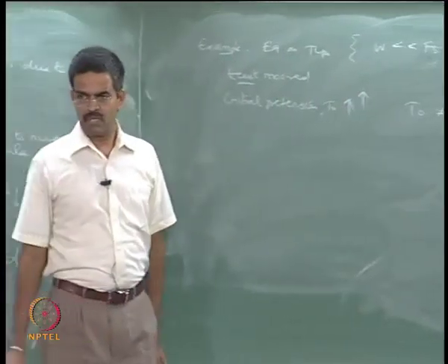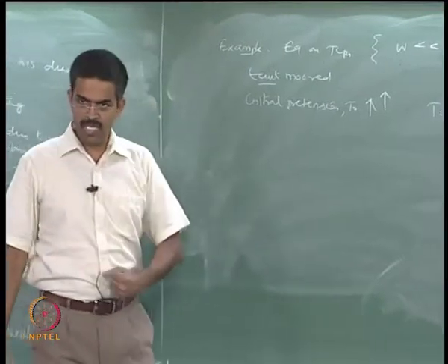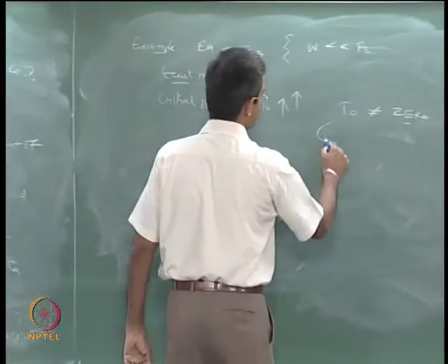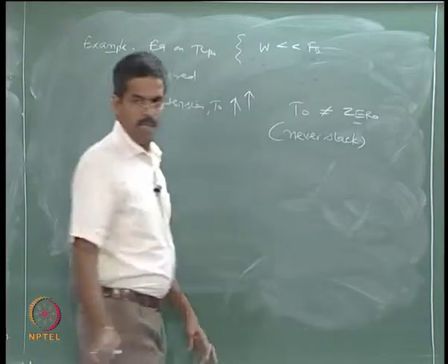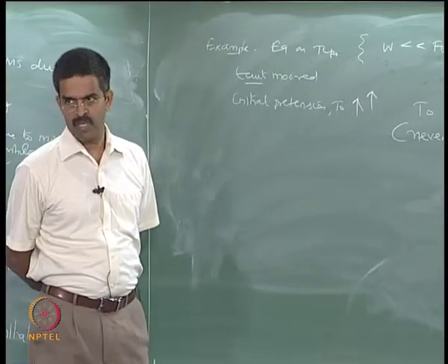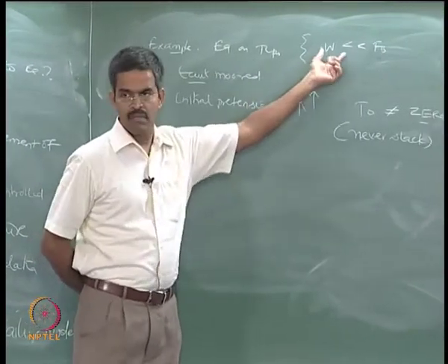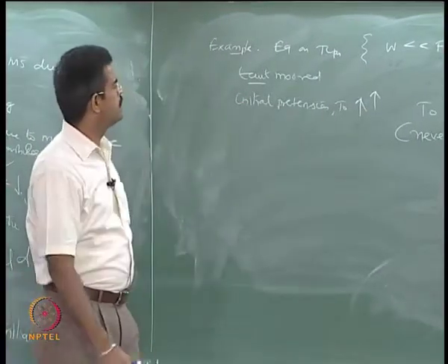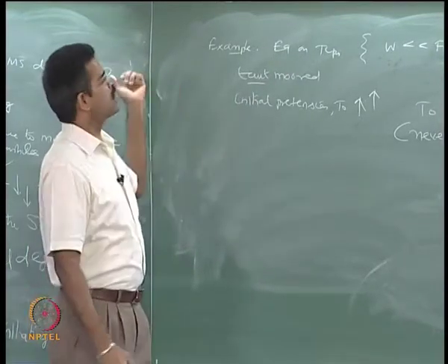What do you understand by this? The tethers will never slack; they will always be in tight mode. There is always an initial tension given to them, and that value is pretty high compared to the weight of the platform. That is the design phenomenon of a TLP actually. So, in such structures, how will earthquake loads become significant?